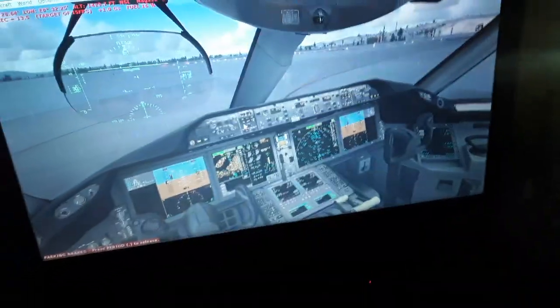We can also see in the navigation display the other aircraft that fly around our own aircraft, using the transponder. The transponder transmits our frequency to other aircraft and air traffic control and receives from the other aircraft. And you can make calculations using its computer about the other aircraft's position, the distance from our aircraft and bearing, also the altitude difference from our aircraft, how many hundreds or thousands of feet are above or below our aircraft.